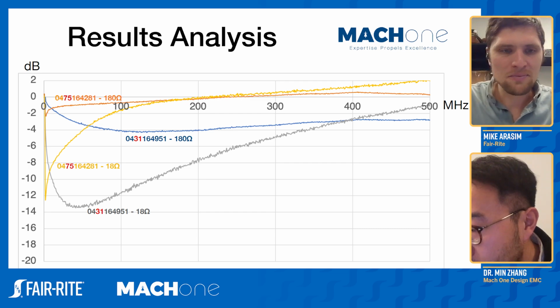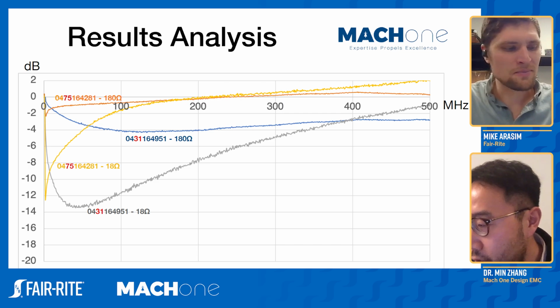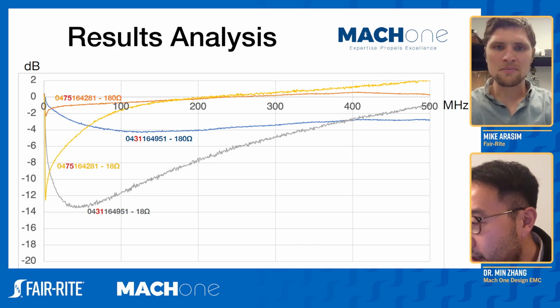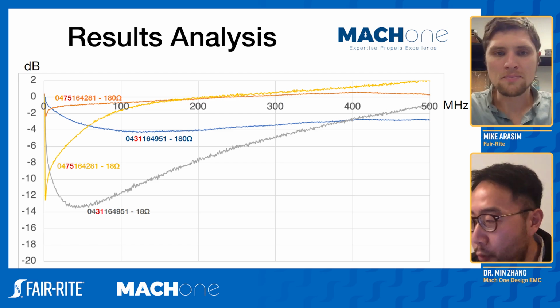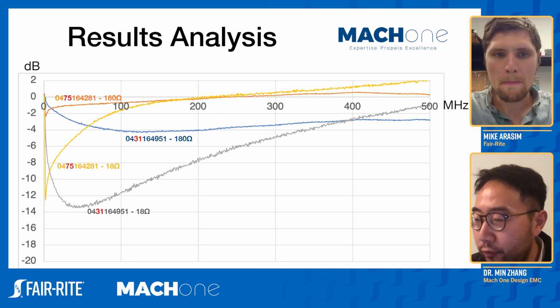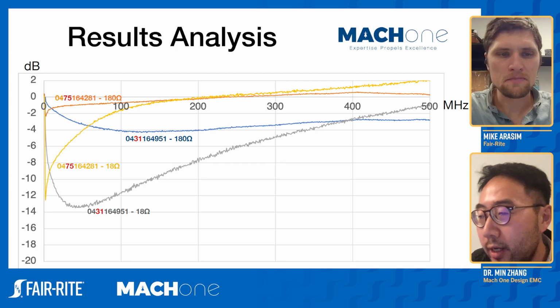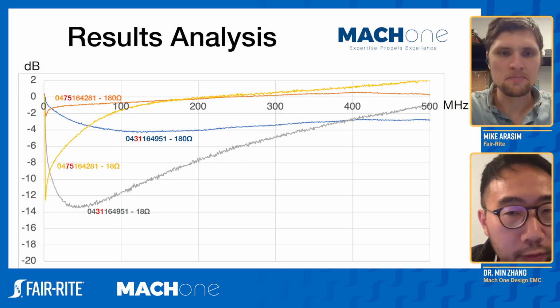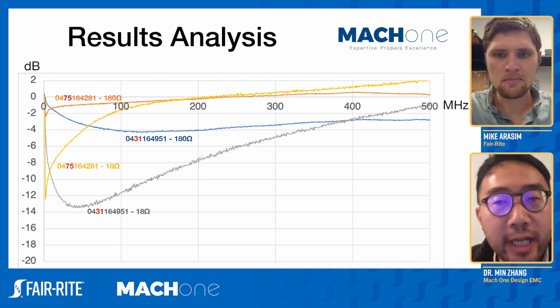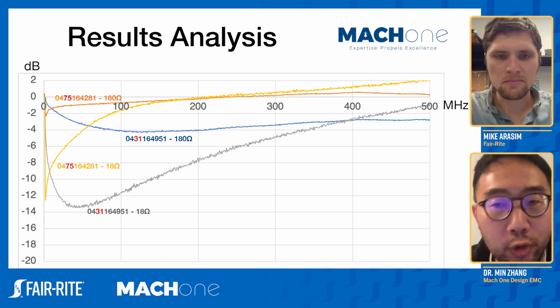It really shifts. It depends on the circuitry, and here again, when we look at 300, 400 megahertz, if you look at that wire, a few inches long, the impedance of the wire perhaps already exceeds about 150 or 200 ohms.